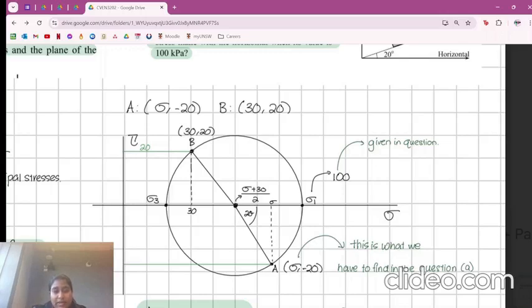The 2 ends of your circle on the horizontal plane, your sigma 3 and your sigma 1 value, are your minor and major principal stresses, and they are the points or the orientations at which the shear stress is 0. And then your radius here is representative of when your shear stress is at the maximum value, right? And then your middle point here is just your average normal stress.